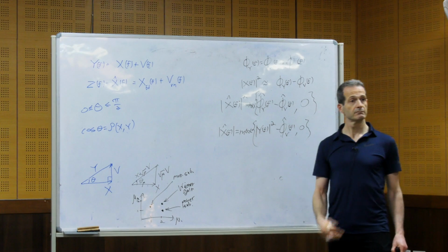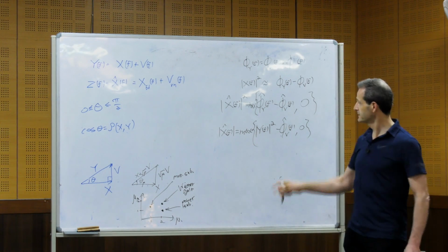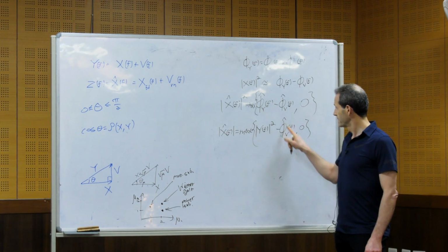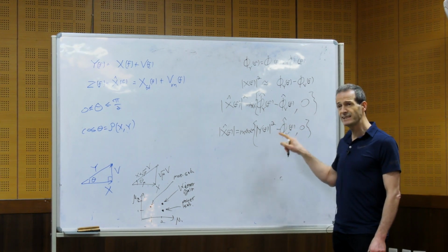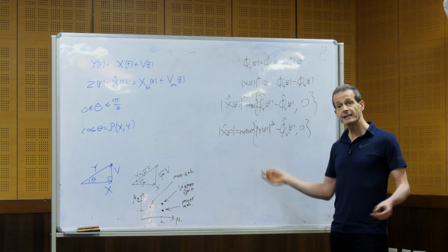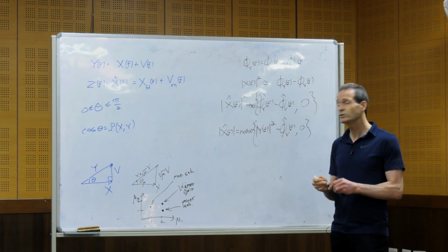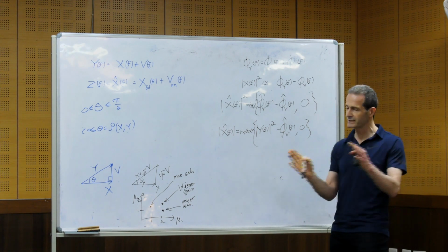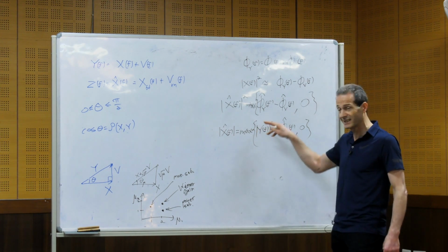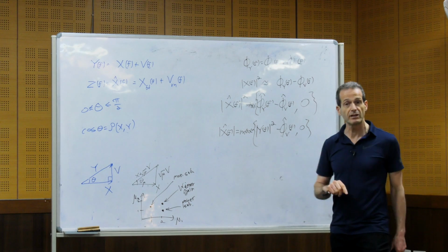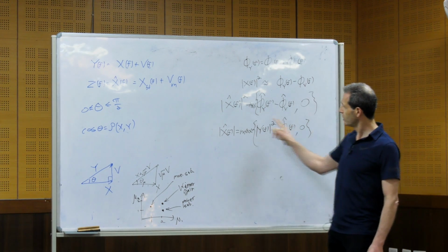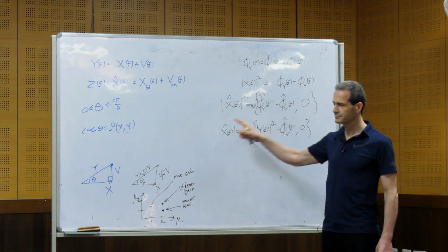Okay? This is easy. I have the measurements. Regarding the noise variance, in many applications, it's also easy to find it because the noise is stationary. And maybe during intervals where we don't have the signal, we can estimate the variance of the noise. Okay? So this is called power subtraction.